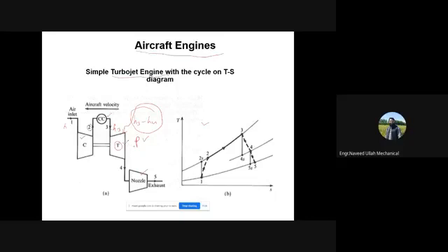And you know what is the definition of thermodynamic work, right? That is basically used for lifting or lowering of a weight. But here the pressure drops, okay, but there is no thermodynamic work involved here. And the reason is very obvious, because here only the working fluid or the exhaust is accelerated in the nozzle, okay. So if for example here you are having the pressure P1 and this velocity V1, so at exit you